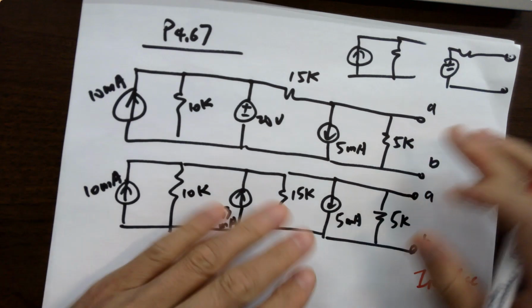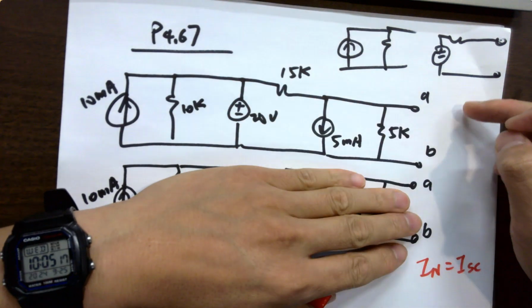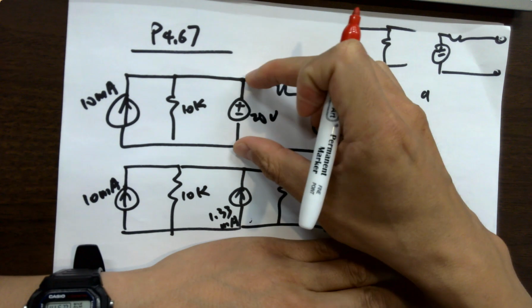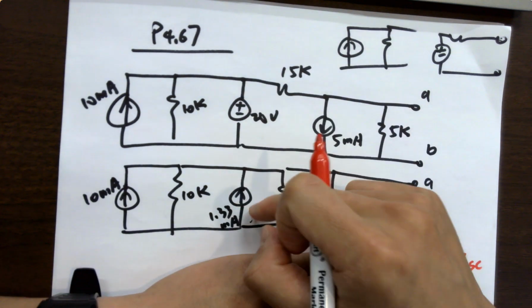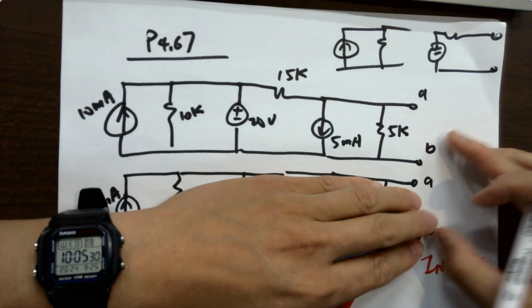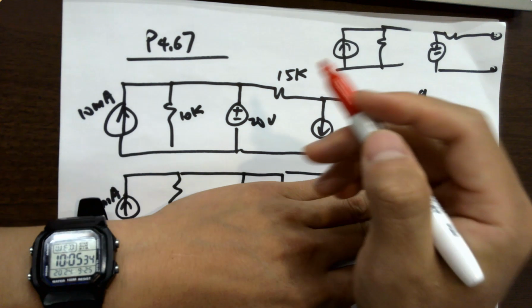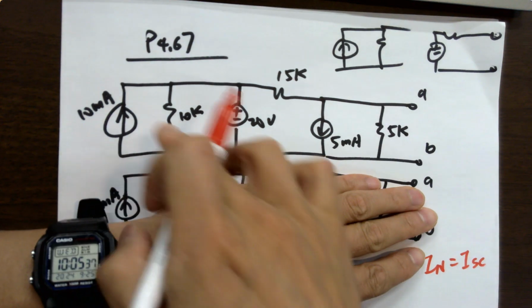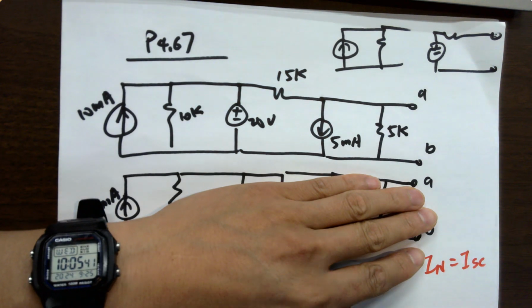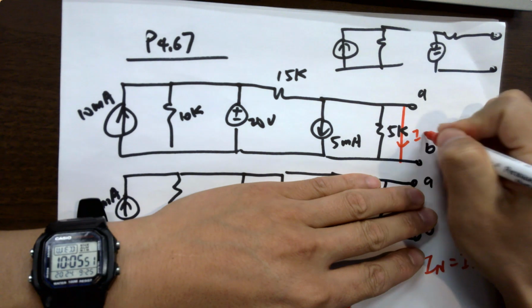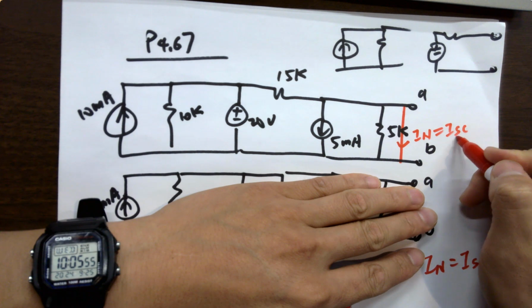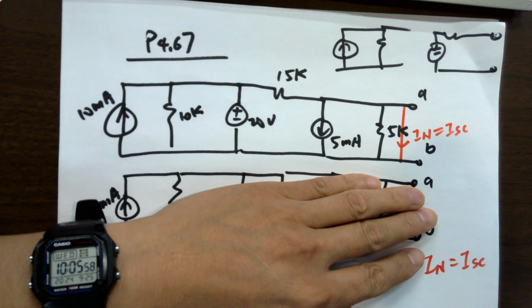And in other circuits, so this is the original circuit. Before you do the transformation, like I said, here you have a voltage source, you'll see in a bit. If you have a voltage source bridging these two terminals, you cannot do the transformation from here to here. I'm going to show you why, okay? So we have learned that, and it's working, no limitations on this, okay? If you have the original circuit without any transformation, no source transformation, just the original circuit, fresh, okay? You draw a wire across these two terminals, and the current flowing through this is going to be IN or ISC. So short circuit or Norton current. For sure, no limitations, okay? It's going to work always.